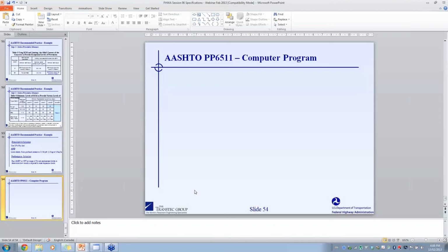This test basically consists of running an oxide content, if you like, by chemical analysis. And in that test procedure, there's a chart where you can plot the result of calcium oxide over magnesium oxide, plotted against the aluminum oxide. And on that chart, you can actually find an area where the experience from testing aggregates shows potential alkali carbonate reactivity, at least in Canada.